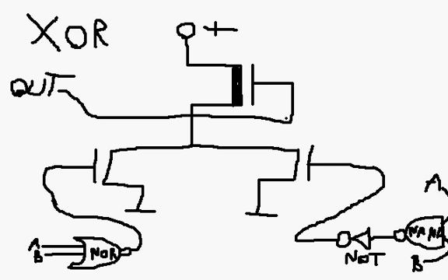Very nice. Okay, so the truth table for XOR, of course, looks like this. It's exclusive OR, meaning if one or the other of the inputs but not both, then true, output of 1. So these give you 1, and if both of the inputs are the same, then you get a 0.